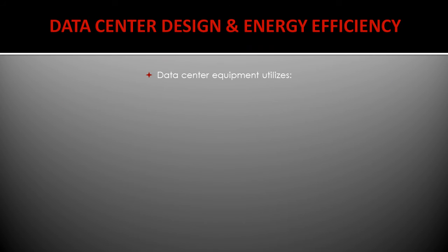A good design concept will recognize that there will be high electrical generation and usage and will put in place backup generators, a good power conditioning system with efficient ventilation and air-conditioned cooling, and will also include, as a must, a waterless fire suppression system that minimizes damage to computer equipment and buildings in the event of a fire.